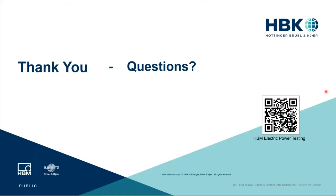And last question, can you periodically measure efficiency to do a health check? Yeah, totally. And we do have people who, every 100 hours, run a brief efficiency map and compare those points, or you can continuously measure efficiency and actually use that as a thing you track. For demagnetization, that can be a really powerful tool. So I would say efficiency is absolutely a variable you should measure. And with the eDrive system, you really have the accuracy to trust a very tight band of how that efficiency is behaving.